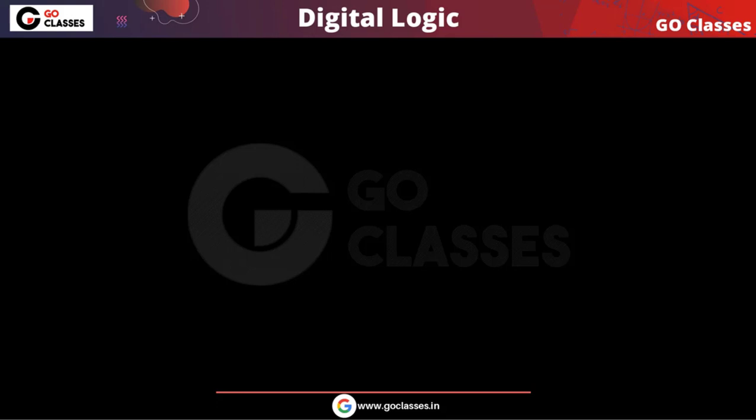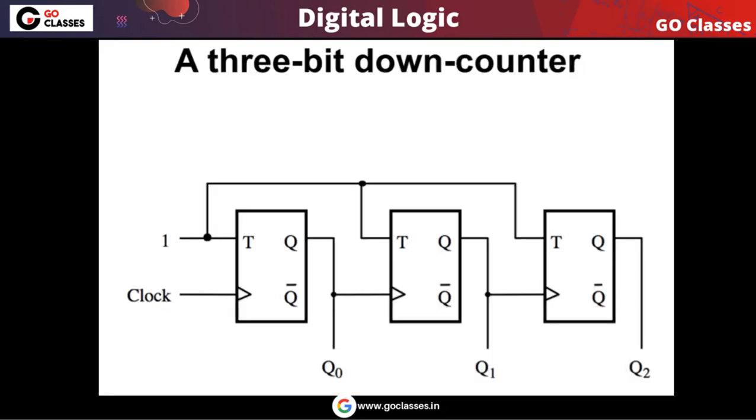I hope the points about what a transient state is are clear. Let's see another example. Here we have 3 T flip-flops. The clock is applied to the first flip-flop, the output of the first flip-flop works as clock for the second, and the output of the second works as clock for the third. Let's assume these are q0, q1, q2, where q0 is the LSB and q2 is the MSB.